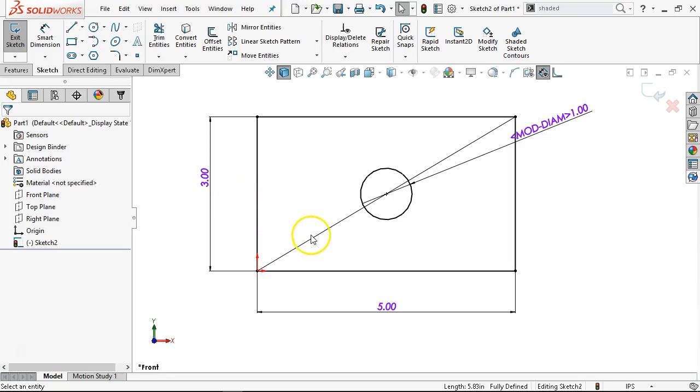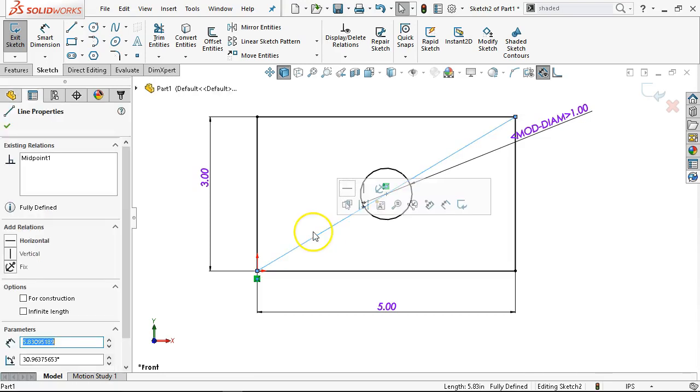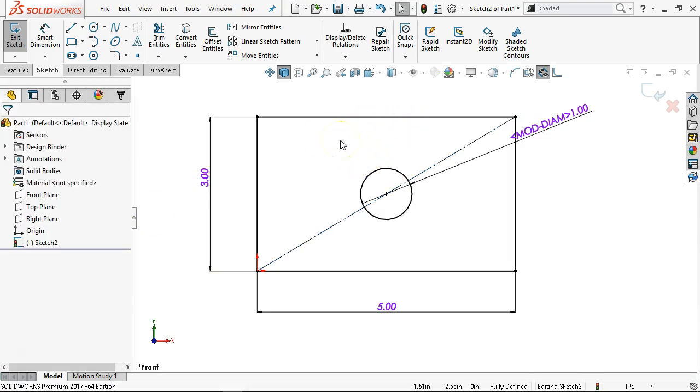I don't really want to make those additional selections, so the other option is I could toggle back, or I can come over to the property manager, and under the property manager, go for construction. All right, now I have 2 regions, but because this is a singly nested sketch, meaning that I don't have anything inside of the first nest, this will extrude without an additional selection.